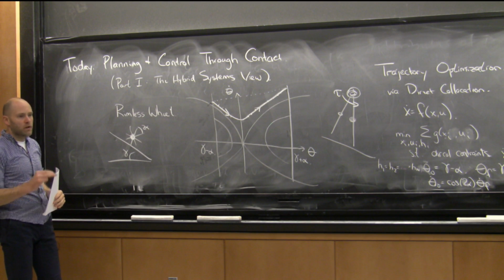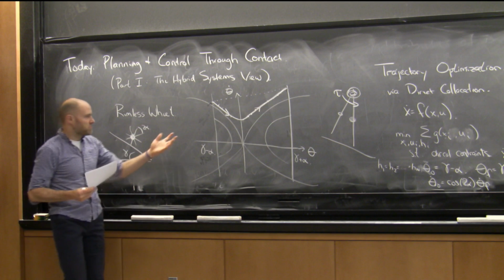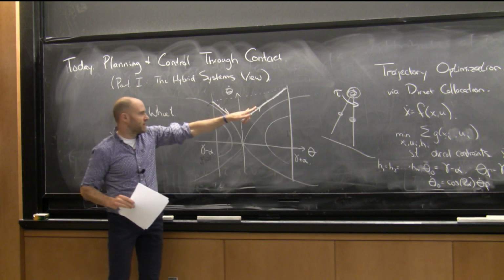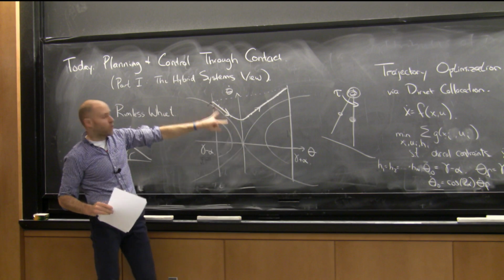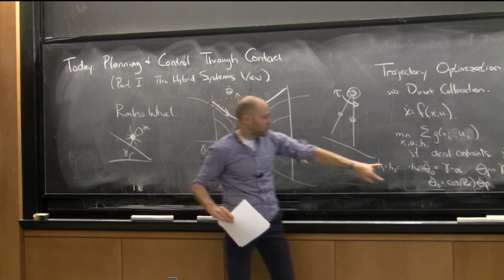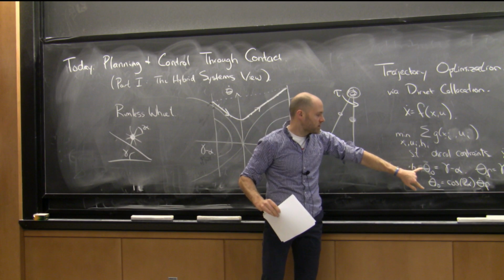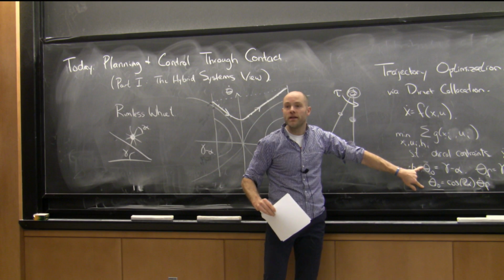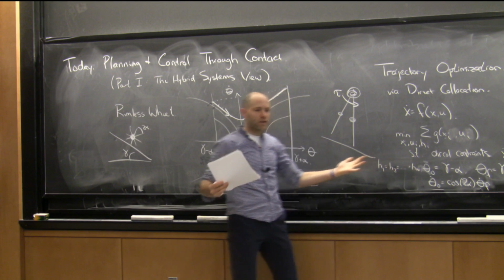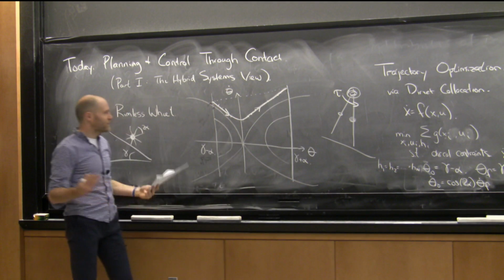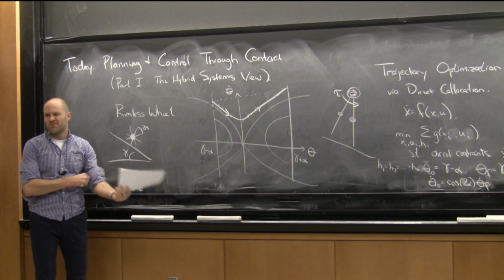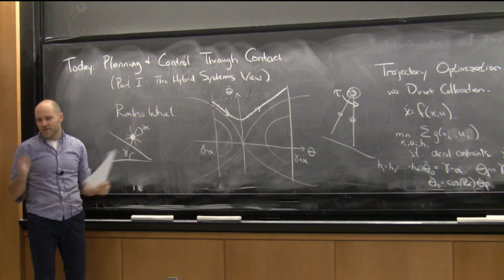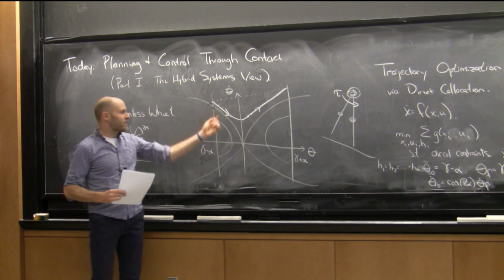Okay, so this is all typed in, but it'll just make this plot, so I guess it doesn't really matter. But it's like 3 lines more than what we did before, which is just adding these constraints that enforce periodicity and enforce the impact equation. Okay, so trajectory optimization rules, right? You can throw in really hard problems, including collision, and it still works. Sometimes it can't find the solution, but when it's good, it's great.